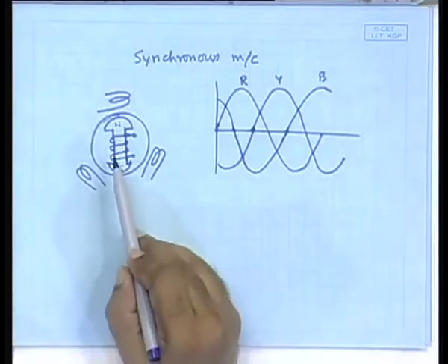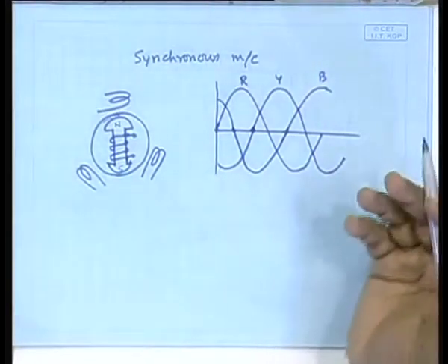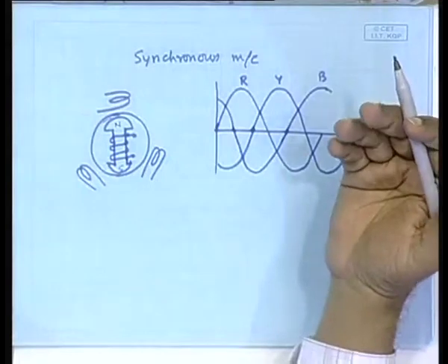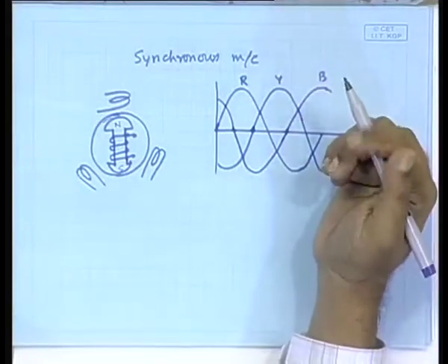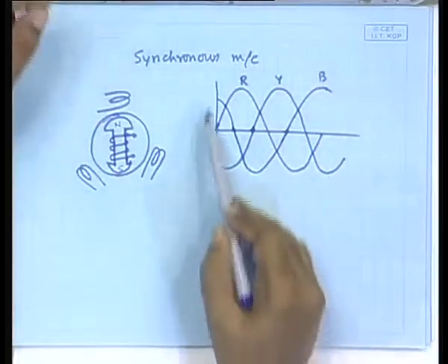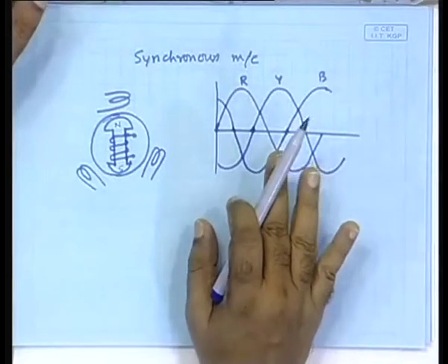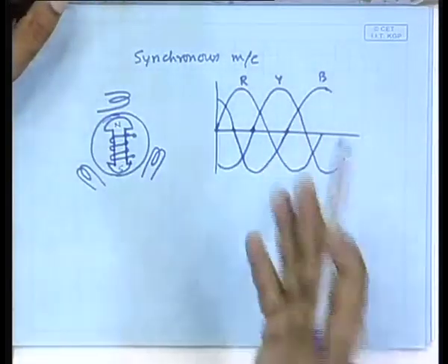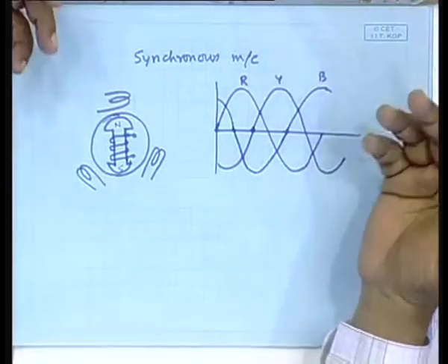Now, this voltage, as it is generated by this mechanism, will be something like the open circuit voltage. If you do not connect a load, then that will be the voltage that will be seen. And as you know that such sinusoidal voltages, from now onwards we will treat things in single phase, but we will always remember the thing is in 3 phase, because the circuit diagram, the equivalent circuit, and the phasor diagram are always drawn in single phase.